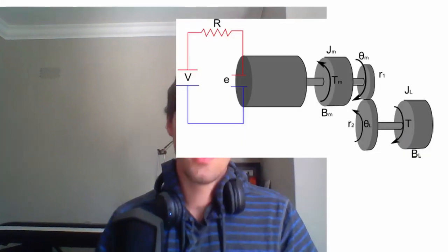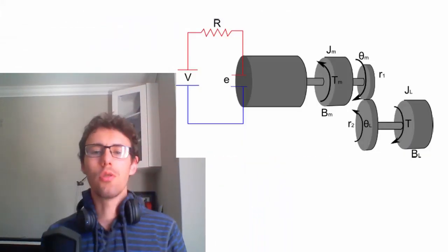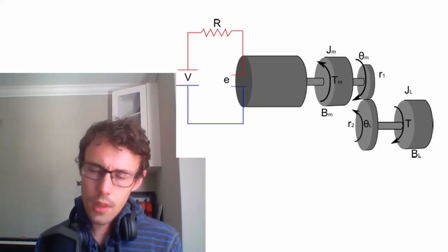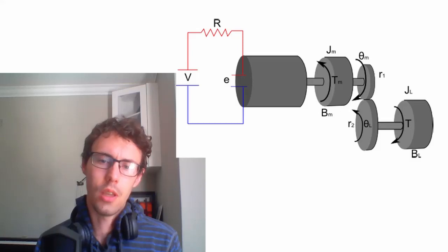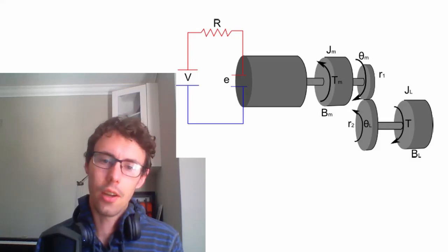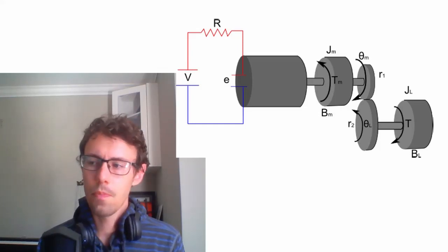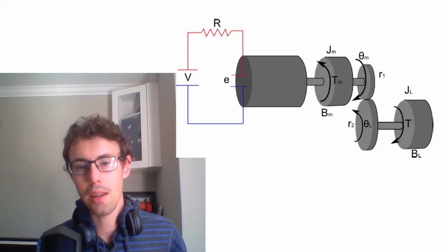It has to be able to stop the turret from minus 35 to 35, so that's going to be done with the limit switches. Then to design the full control system, you have to make a mathematical model of it, and for that you need some properties from the motor, the gear ratio, little things like the expected viscous friction, torsional rigidity of the system. So that all comes from the mechanical system that we discussed.